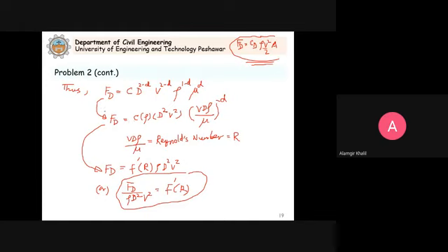Now in dimensional analysis, we come up to here. But in order to proceed further, we have to determine experimentally the value here. You see, I write down here f prime r, it means that there is some coefficient here which is a function of the Reynolds number. So we say that this must be determined experimentally.